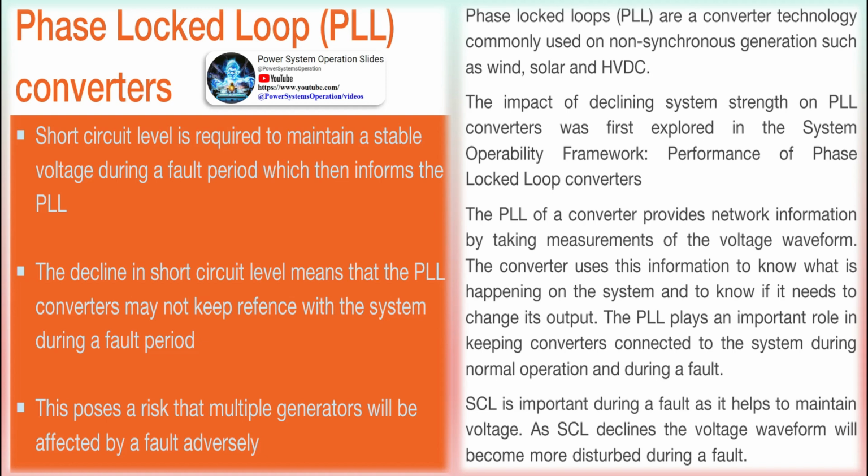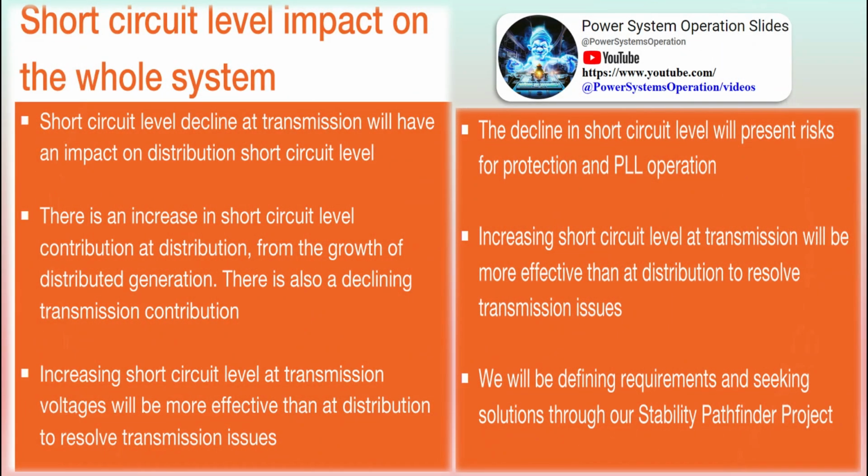circuit breakers and fuses. Results of the fault current calculations are also used to determine the required short-circuit ratings of power distribution system components, including bus transfer switches, variable speed drives, switchboards, load centers, and panel boards. In calculating the maximum fault current, it is necessary to determine the total contribution from all generators that may be paralleled and the motor contribution from induction and synchronous motors.